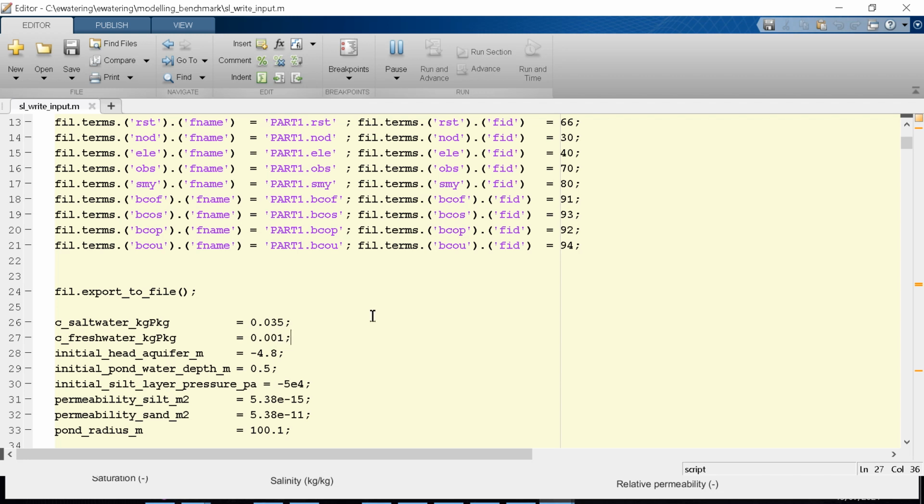The reason that we don't put it as 0 is because sometimes there are some kind of numerical oscillations. So let's say if you have a 0, the oscillation could change the value from a negative number to a very small positive number, right? But the problem is that if your concentration becomes a negative number, it doesn't have any physical meaning.